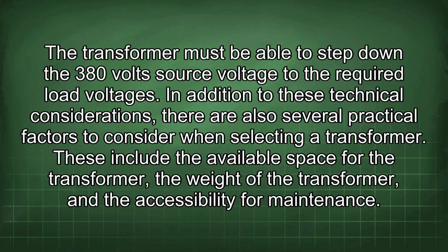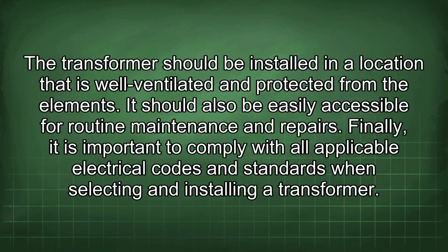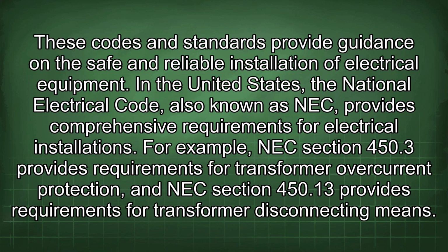These include the available space for the transformer, the weight of the transformer, and the accessibility for maintenance. The transformer should be installed in a location that is well ventilated and protected from the elements. It should also be easily accessible for routine maintenance and repairs. Finally, it is important to comply with all applicable electrical codes and standards when selecting and installing a transformer. These codes and standards provide guidance on the safe and reliable installation of electrical equipment.